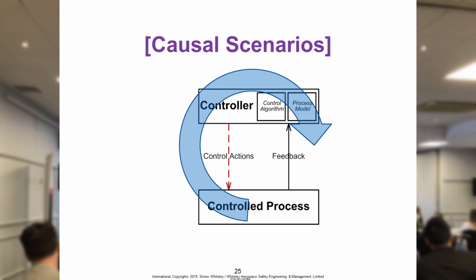And if you go from a manual car to an automatic car or the other way around, you'll notice, when you go to press the clutch, you end up through the windscreen. That's because your control algorithm is inappropriate for that particular circumstance. Then you have what's called the concept of a process model, and that essentially is a model of what's happening in the control process. And if this is a human controller, that would be one of your mental models. And they are updated by feedback about the control process, and ultimately that's the control feedback loop.